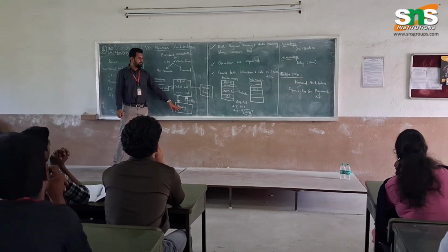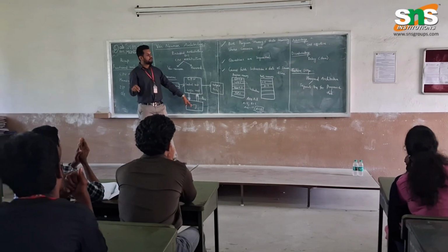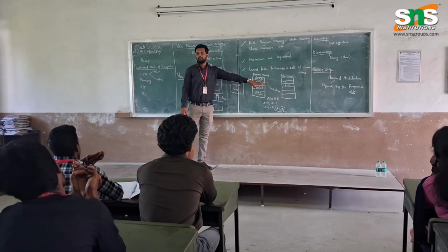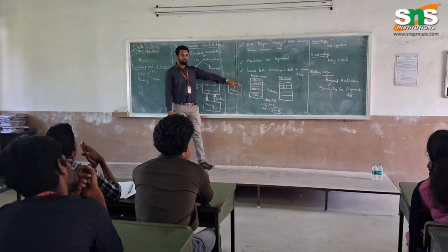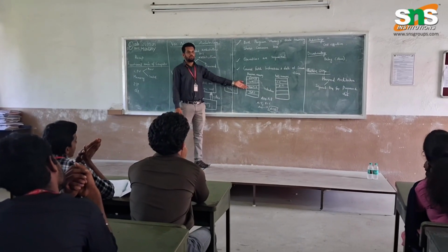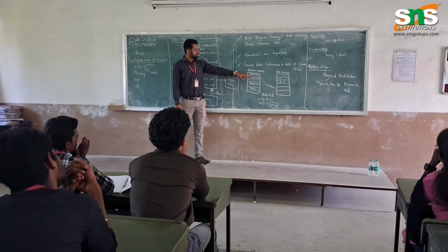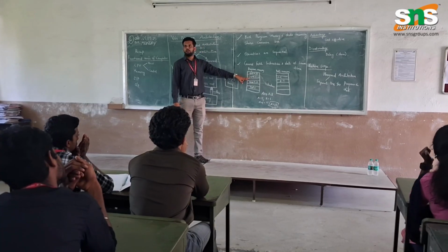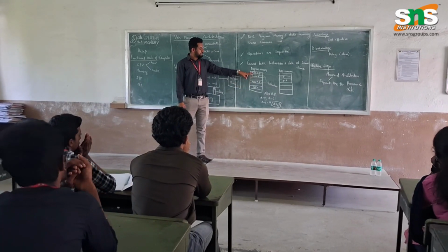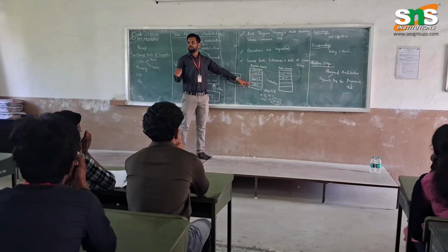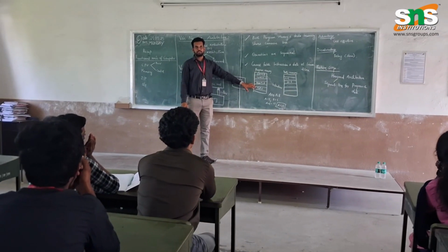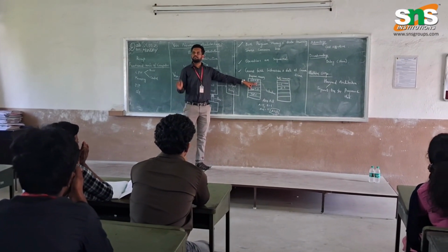This memory will be split into two types: program memory and data memory. For example, you are going to do some operations, addition, loading, or moving operations. So you will have instructions like add, load, move. These are called instructions. Only the instructions will be stored in this memory. Instructions like add A comma B is an instruction.